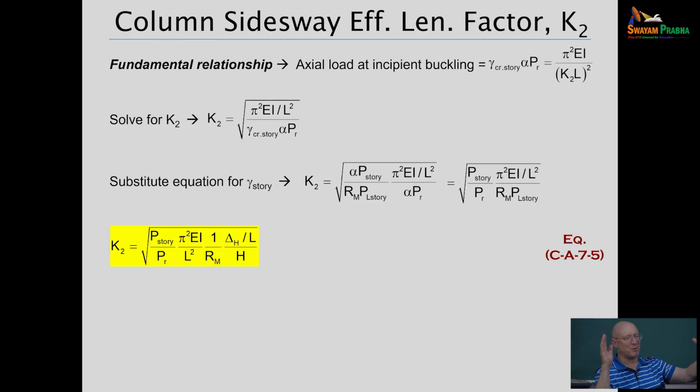That very light member on its own doesn't have much stability, so the rest of the sway frame is essentially bracing that member. So it's a sway frame, but you're actually getting an effective length factor less than 1 for that very light member. That's confusing to a lot of folks because we're used to using tools where we say, oh, it's a side sway, K is always greater than 1. No, it's not.